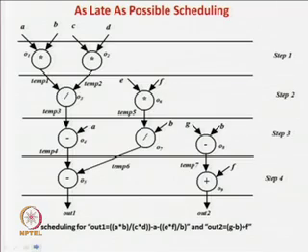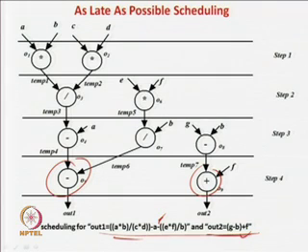It is very similar, so we will just see this with the same example. Again the same example is like this. In this case you have to go the reverse way. You know that O9, the addition operation, and O5, the subtraction operation, just generate the output, so you do not need to worry about anything else. You can schedule them at time step number 4, because we have already seen that you should not consider time step 3, since for this scheduling problem 3 will result in an infeasible situation.